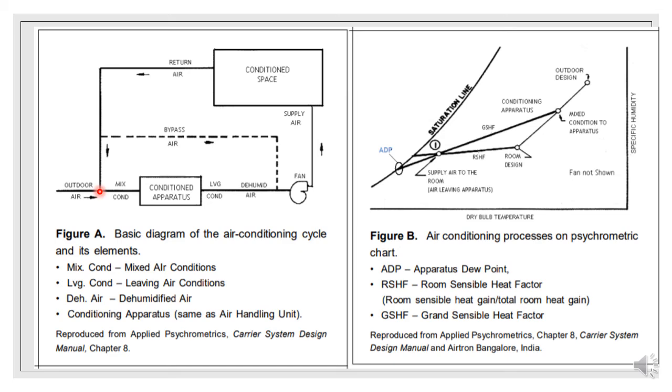And in air conditioning, the total air in circulation consists of about 80 to 90% return air, which is recirculated, and the balance being outside air for ventilation, about 10 to 20%. And with the outside air being hotter and more humid, which means it has higher enthalpy than in the conditioned space, its flow rate is kept to the minimum to reduce the air conditioning load.